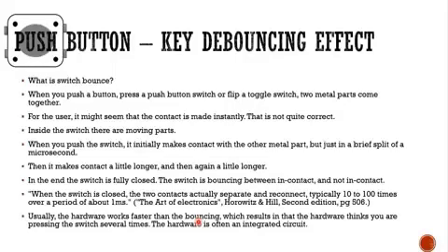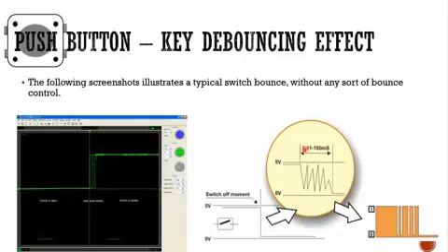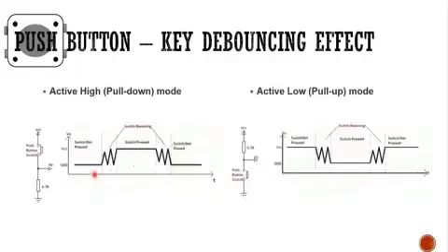Because of the speed of the hardware, you can see the vibration happen here, in the range between 0.01 and 100 milliseconds. It normally happens during starting and also during ending, during the transition from low to high or high to low. This is the period when the bouncing effect normally happens.